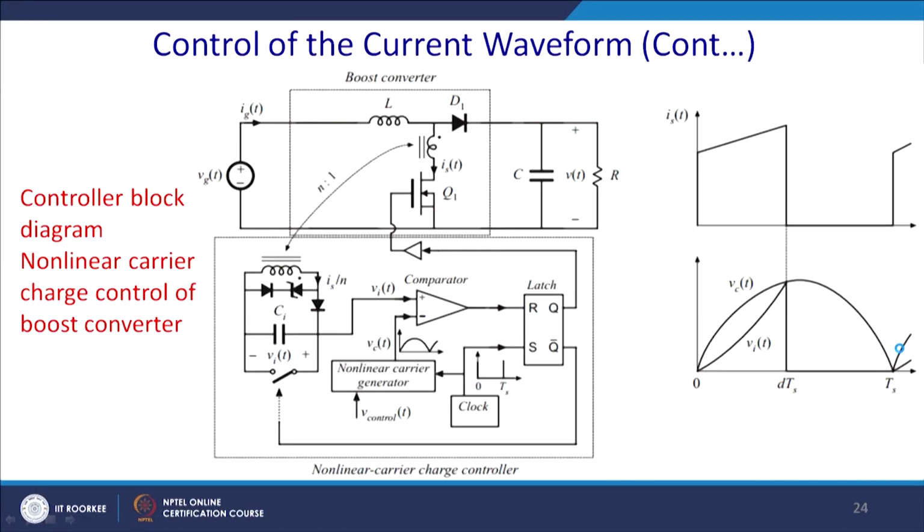So, phase shifted different carriers are also possible, so that you have a petals kind of waveform. Another petal may be phase shifted by 30 degree, you may superimpose it, and thus what happens, you get a better THD. So, this is the control of the current waveform.